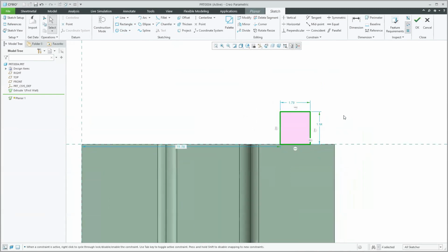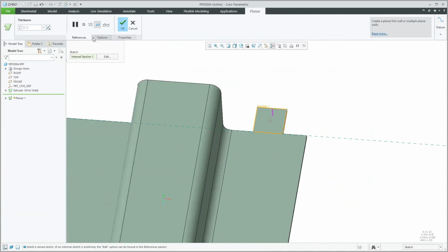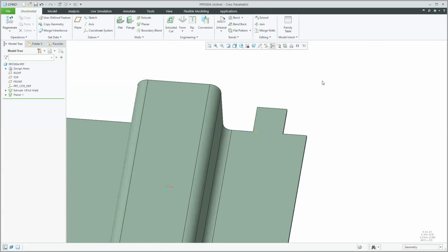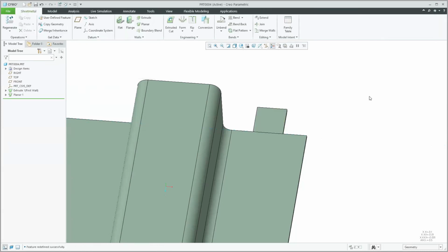What I wanted to show you is that anytime you reuse one of the primary walls as a secondary wall, there is going to be an option here that will allow you to merge to model. So what's going to happen is this new piece is going to automatically become part of what I already had. Now, if I go back to that wall, edit definition, I could say do not merge to model. And then it's going to keep that piece separate.